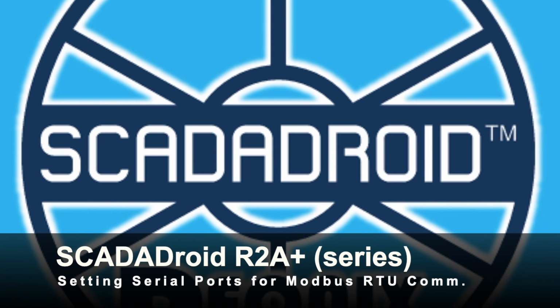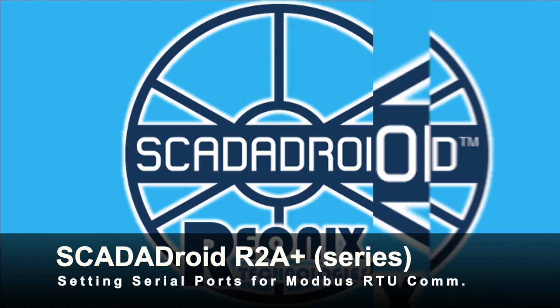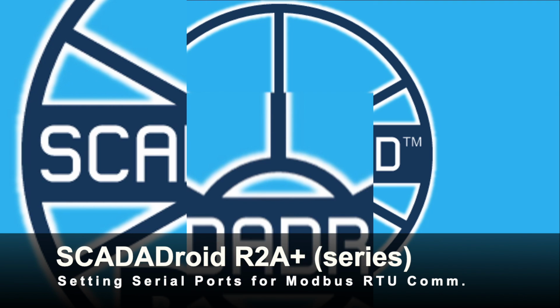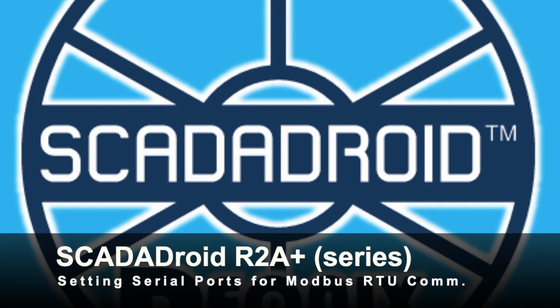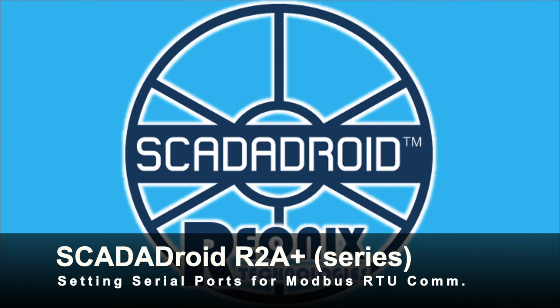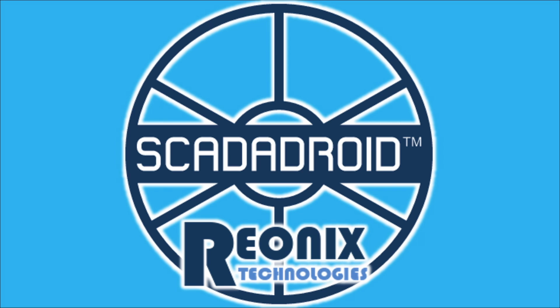2. RS-485 serial ports can go over 4,000 feet, and therefore devices can communicate at a further distance and on a cheaper cable than using either fiber optics or Ethernet with repeaters to get the distance, albeit at a slower rate. And 3. Serial ports are much cheaper to develop and less complicated from a manufacturing perspective, so many manufacturers use them for digital communications.